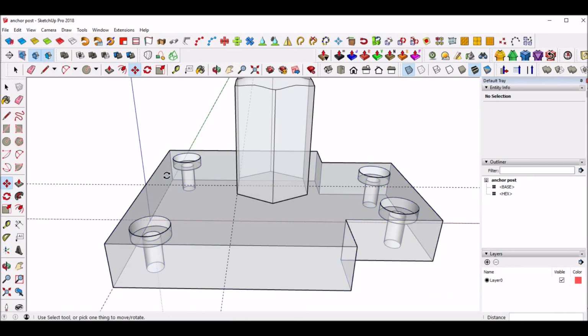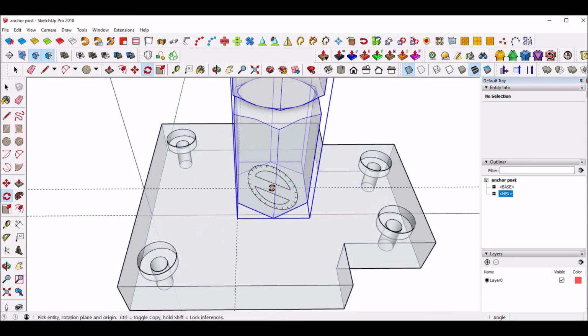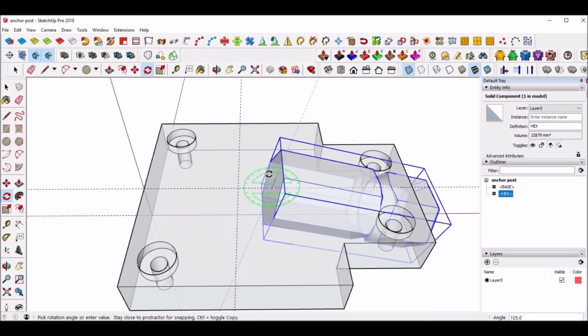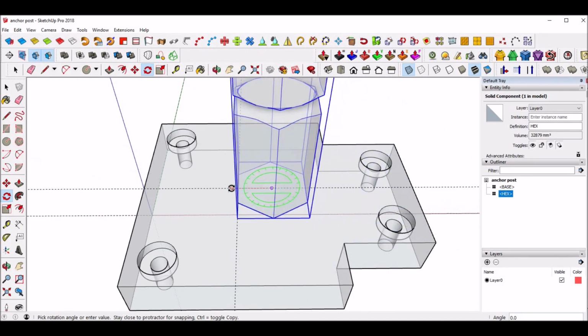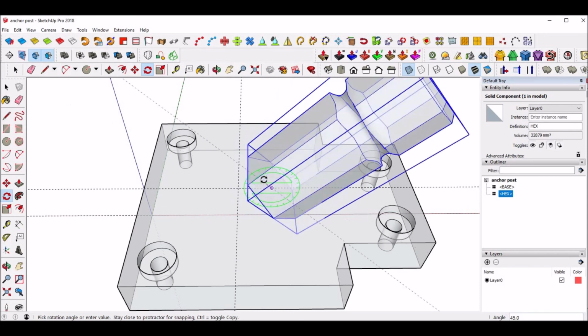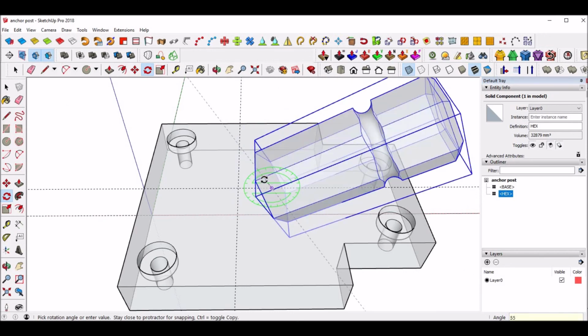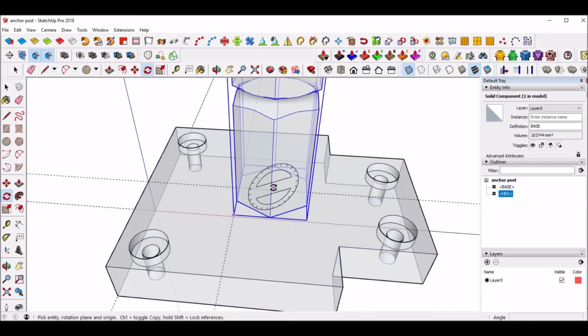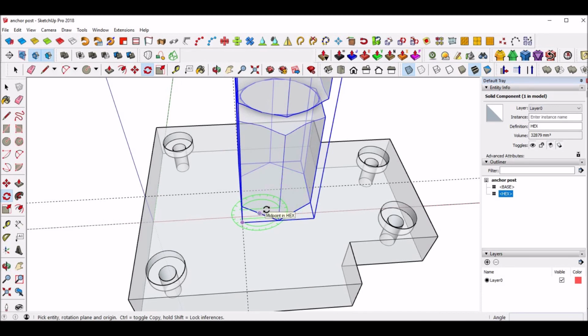Now turn on X-ray because we're going to need to rotate right at the center. Right. Oh goodness, it's a little right there. And we want to do it along the green. Click once and then click again. So we want it to be 55. No, I lied. Sorry. 55 off that end, which means 35. Excuse me. Wow, choking. 35 for up here. Okay.